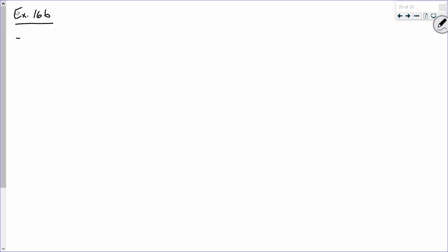All right, so the first thing that we would typically do on a column design problem is determine the factored load. But we really don't need to do that for this because it was given. So PU is 890 kips. Okay? Now, for the column, there's a few things that we can write off the bat. So first off, we know that our yield stress is 50 KSI. And we know the following, okay?